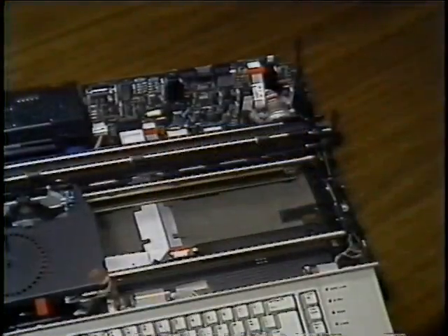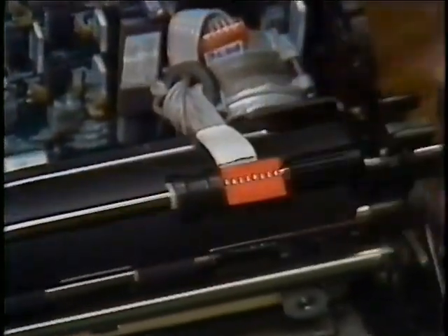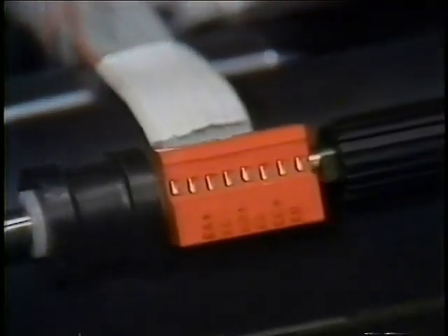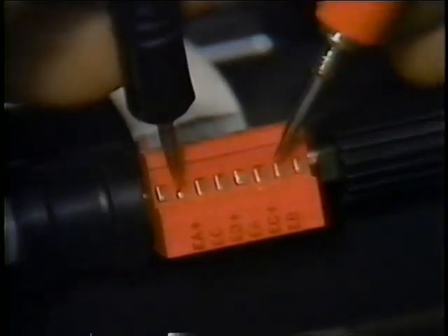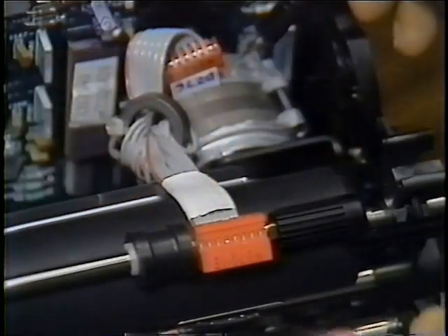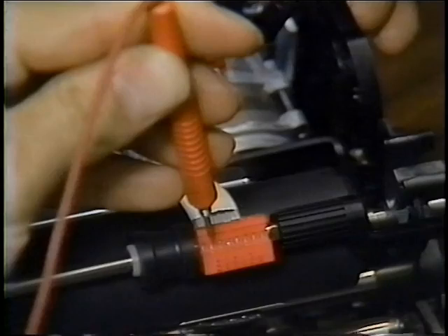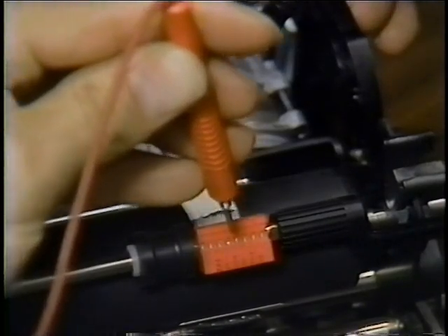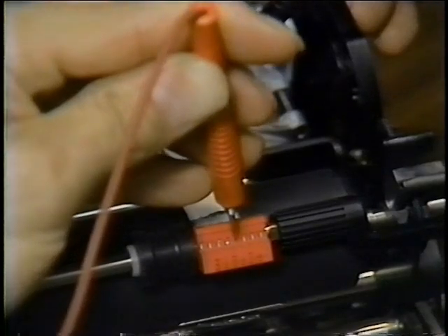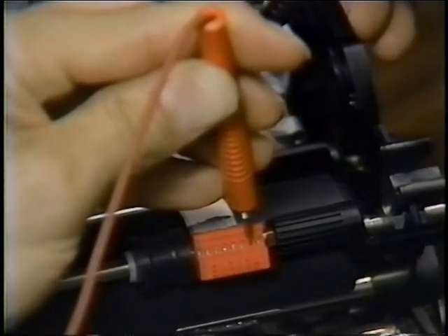To perform the transport motor resistance check, turn the machine off, then unplug the transport motor connector J2P. Zero the meter on the ×1 scale, then check the resistance from pin EA plus to pin EA on the transport motor connector. The resistance must read from 4 to 6 ohms. The resistance reading should be in the same range for EC plus to EC and EB plus to EB. Next, check the resistance from each pin on the connector to the motor housing. There must be no continuity from the pins to the motor housing. This ensures that there is not a short in the motor.